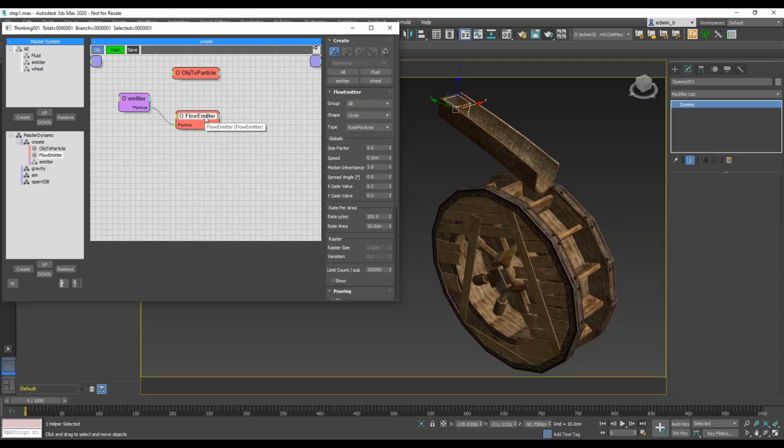Now the next step is, what do we want to do? We want to create our fluid particles, and the fluid particles should go into the fluid group. And I want to have the raster because I like that more, and I want to have the size of 25, and also the particles should have a speed so that particles move when they are created.